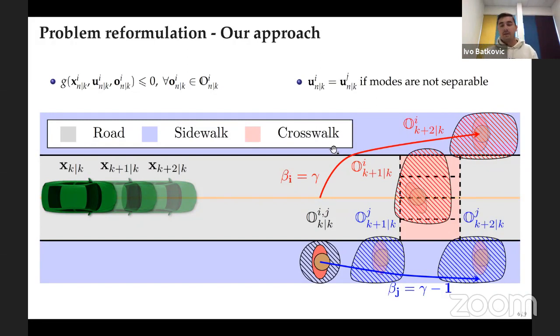In this case, you have two scenarios. You have one scenario where the pedestrian turns left, one scenario where the pedestrian goes straight, and then you also have the probabilities here. So we split up these scenarios for each MPC problem, and for one scenario, we just optimize over one sequence where the vehicle stops. In the other scenario, we optimize over a sequence where the vehicle doesn't need to stop. And then the key question is, how do you combine these different scenarios and trajectories together?